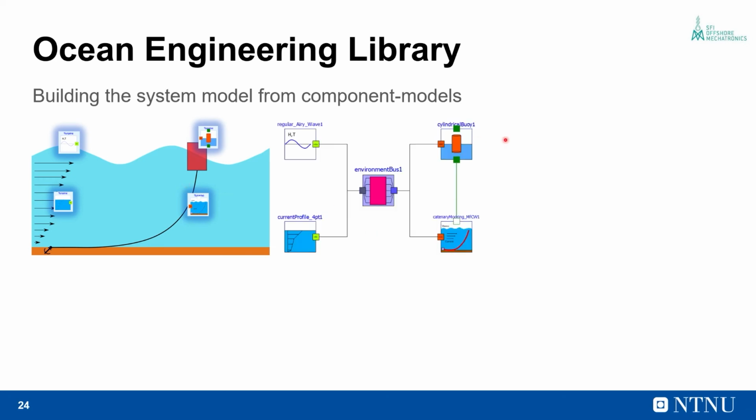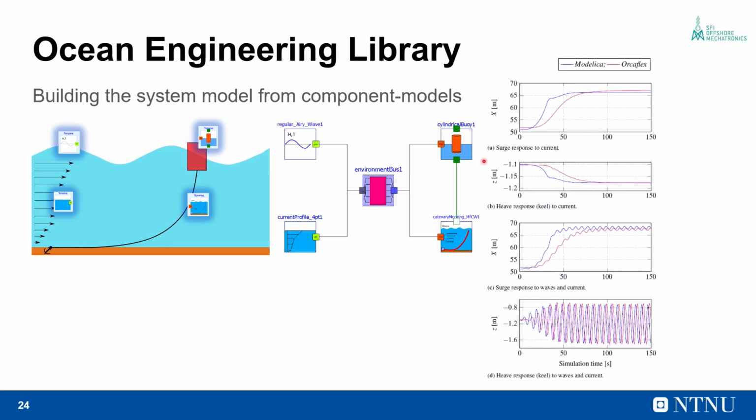And so we implement that in an integrated simulation where the component models for the waves and the current generate the parameters and feed them into an environment bus, from which the buoy and the mooring component models take these parameters and calculate the fluid loads. And we then compare the response of the integrated system with a similar model in OrcaFlex, and we see that there is satisfactory agreement.